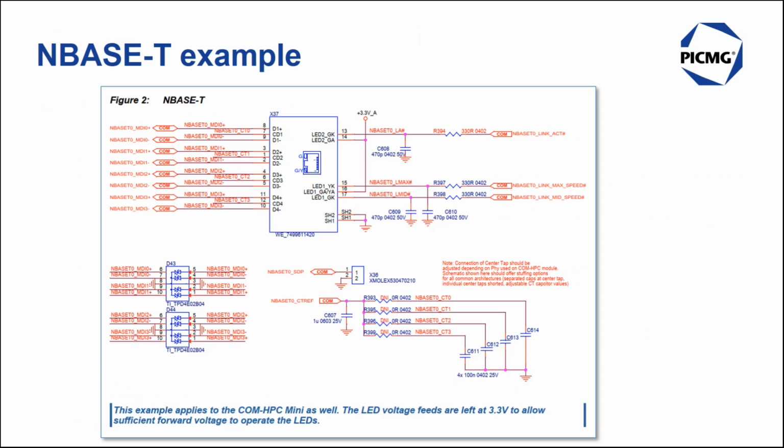There is an example circuit for this interface in the Carrier Design Guide. In general, of course, it must be noted that the schematic examples given in this document are considered correct, but there is no guarantee of this. In addition, the circuits correspond to the time of creation. The carrier designer should therefore check whether the components used in the sample schematics are suitable for his application. For example, it should be checked whether the components can be used in the required temperature range or are available over the entire time of the product. A multi-manufacturer strategy for the selected components also often makes sense.